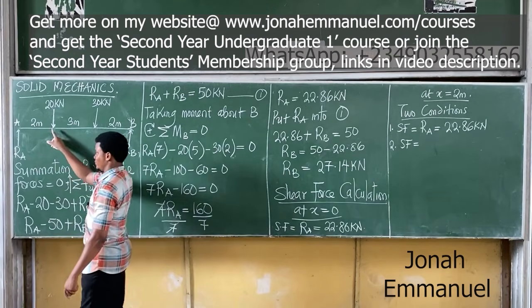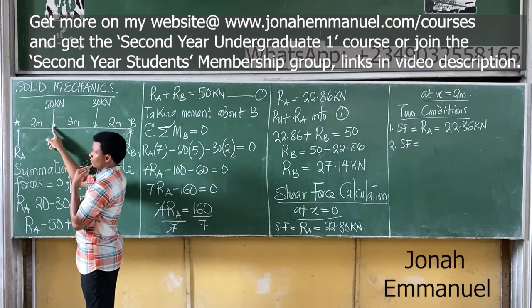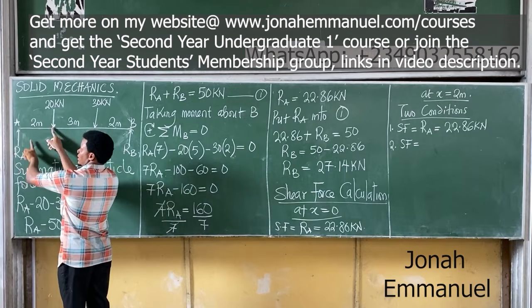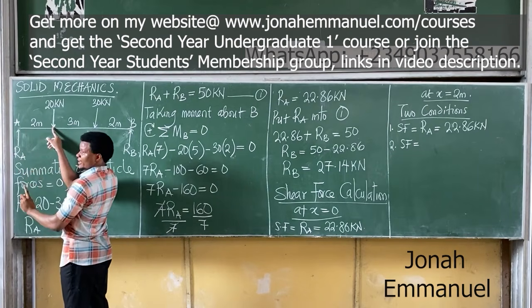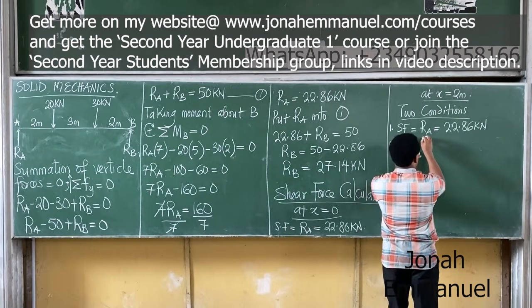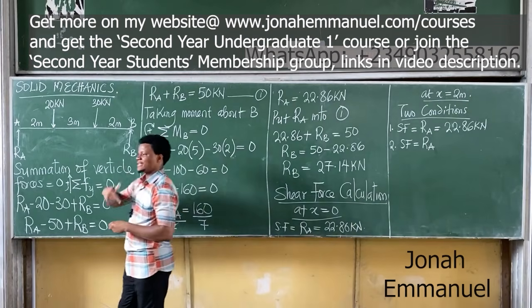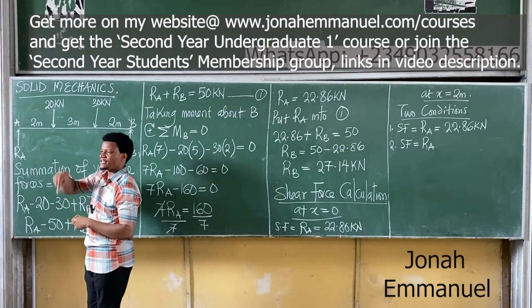Condition 2, shear force is equal to all the forces before that point plus the force at that point. See at this point here. Before this point, what do you have here? RA. It was going up. So before the point, that's simply RA. Again, forces before that point plus the force at that point.